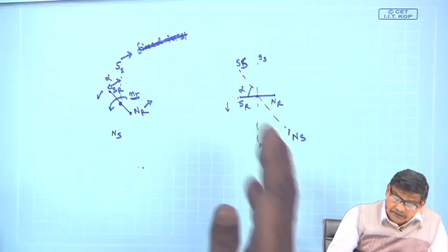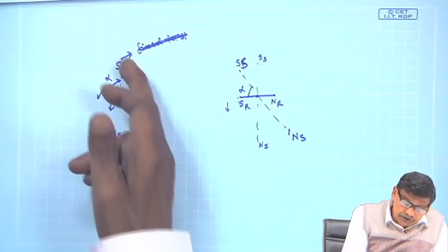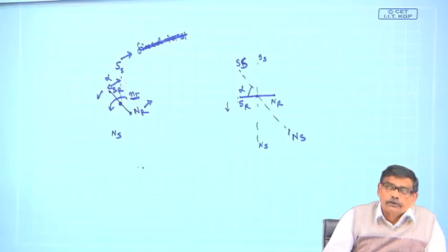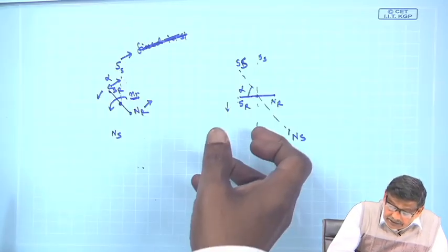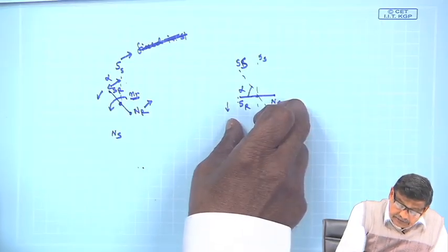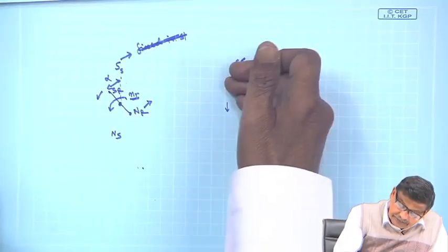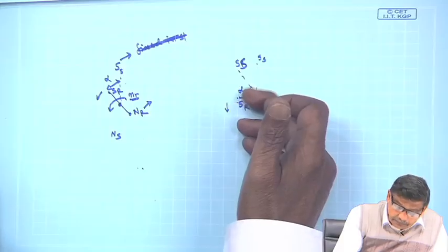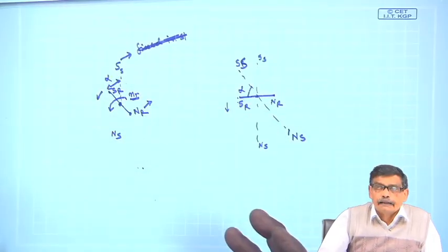So, if somebody says no, the same constant torque is to be produced as when it was producing here, then the answer should be, you not only allow SR NR to occupy a new position like this, also advance SS NS by such an amount that the angle between these two fields, alpha, remains the same.